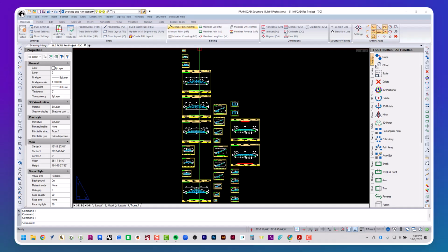In this exercise, we're going to learn how to engineer our upper wall panels to ensure all the loads are transferred correctly through the building. This is done using the panel bracing calculation. The purpose of this is to calculate the bracing requirements for wall framing so that you know where to insert bracing elements, wind force markers, and resistance markers.